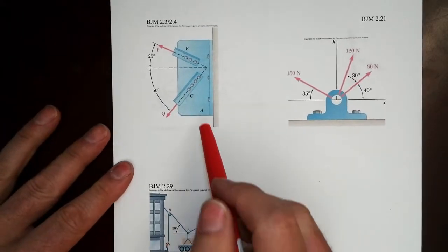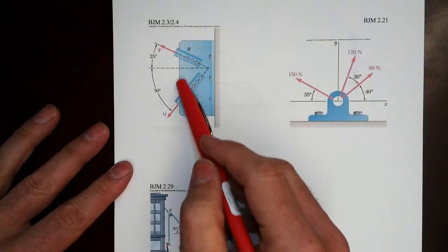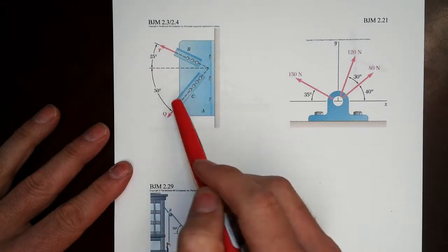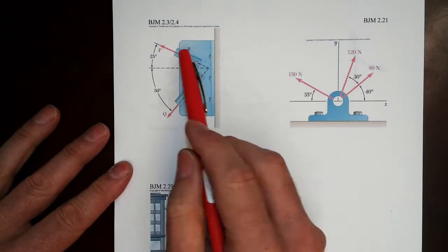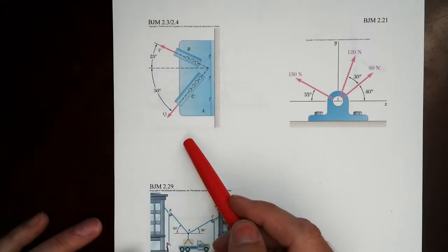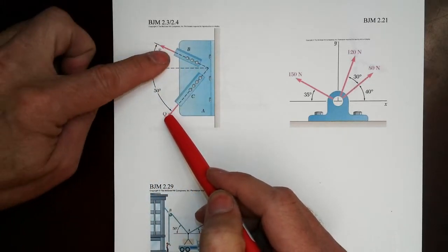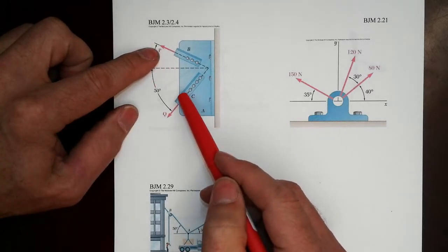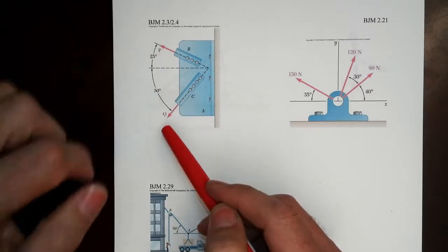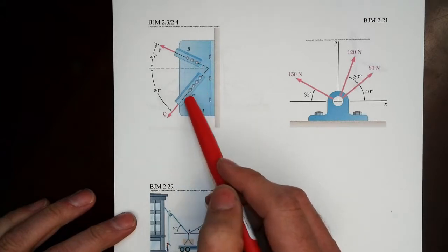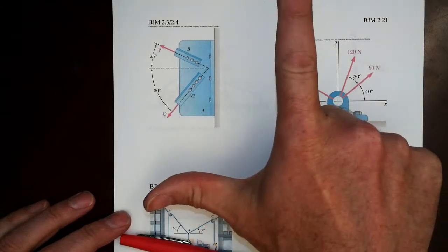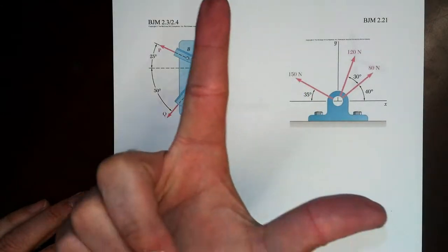Notice we're talking about lines of action and forces, and we're talking about these free body diagrams. All really good stuff. Here is a gusset plate system where two diagonal members are framing into a joint. These dashed lines indicate the longitudinal axis of the member, and the lines of action of the forces are going to go right through there. These are actually internal forces associated with these particular two pieces, which are a representation of what we call in steel shapes angles. Angles have a cross-section that looks like an L.